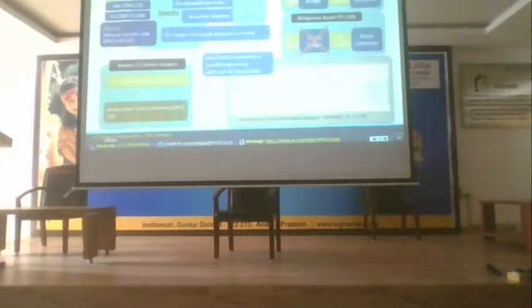There are already various standards set now, but they are still standardizing to make some kind of universal standards, though different organizations have already provided standards: IEEE 1547, SAE J2894, IEC 61000-3-2. These set the limits, and also the US National Electrical Code NEC 690.